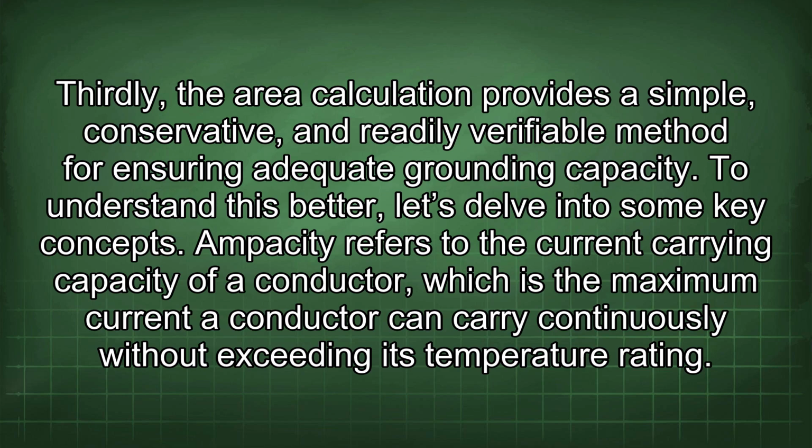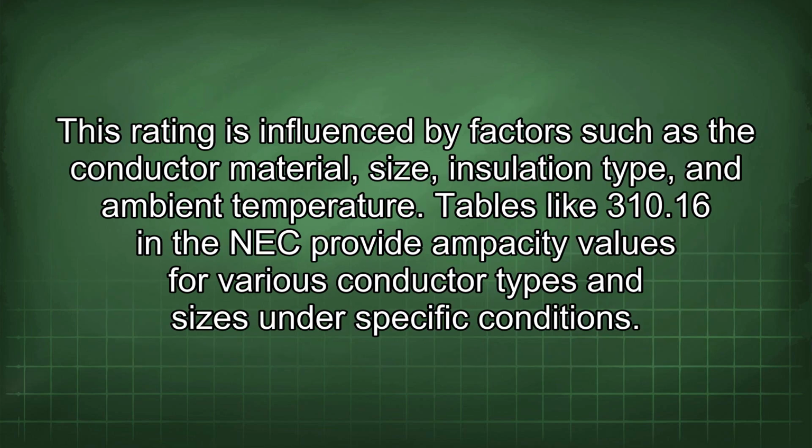To understand this better, let's delve into some key concepts. Ampacity refers to the current carrying capacity of a conductor, which is the maximum current a conductor can carry continuously without exceeding its temperature rating. This rating is influenced by factors such as the conductor material, size, insulation type, and ambient temperature. Tables like 310.16 in the NEC provide ampacity values for various conductor types and sizes under specific conditions.